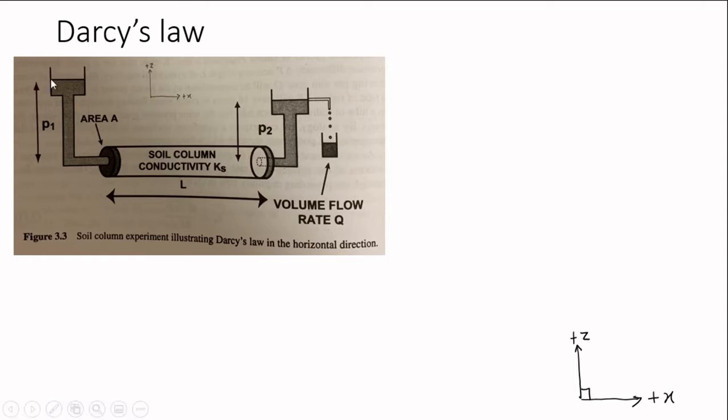Okay, and because the water is flowing from left side to right side, that is a volumetric flow rate. Okay, volumetric flow rate here is measured by using the graduated cylinder, accumulating the water leaving at the reservoir at the right side over time, so you can get the volume. And if you record the time, then you can also get the time. So with the volume and time, you can get meter cube over second.